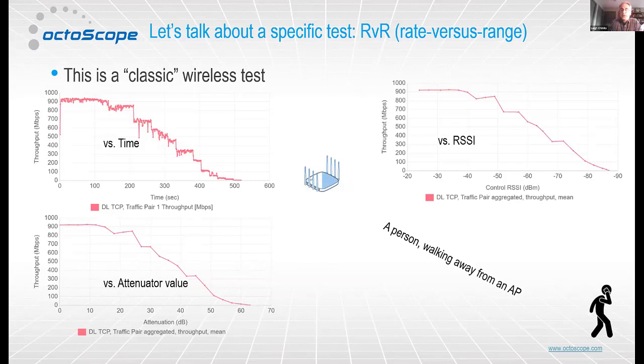So, a wireless path loss model depends on the frequency of operation, the distance, and then the environment in which you're doing the measurement. If you know the transmit power of the device under test, and you've measured the RSSI here, then you know the path loss. And the path loss can be converted into distance just by defining the path loss model that you want to use.